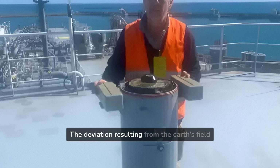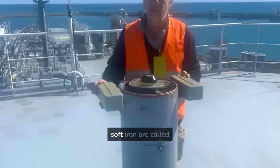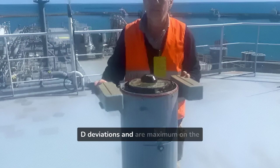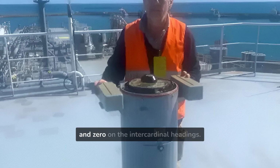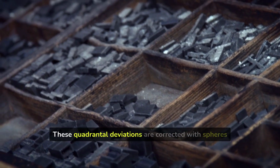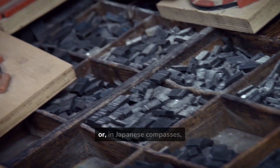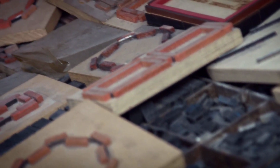The deviation resulting from the Earth's field induction of these symmetrical arrangements of horizontal soft iron is called D-deviation, and is maximum on the intercardinal headings NE, SE, SW, and NW, and 0 on the cardinal headings. These quadrantal deviations are corrected with spheres or, in Japanese compasses, with boxes containing plates inside.